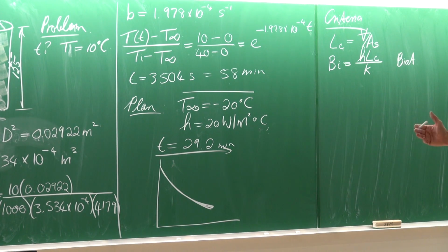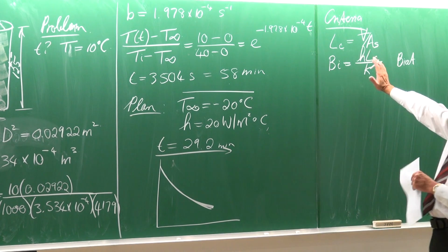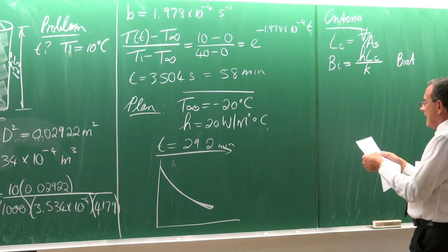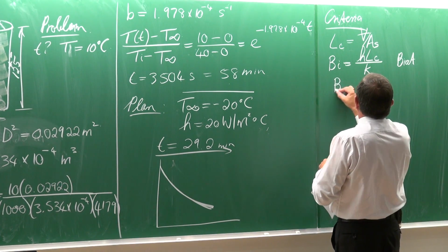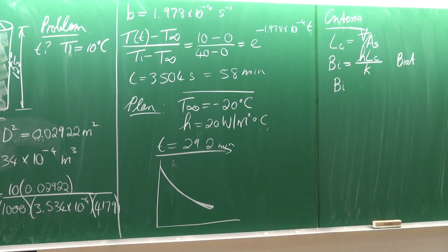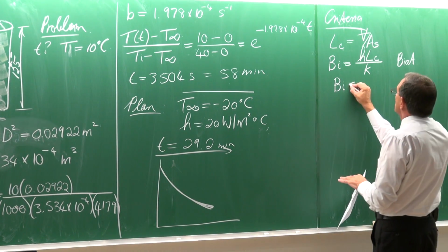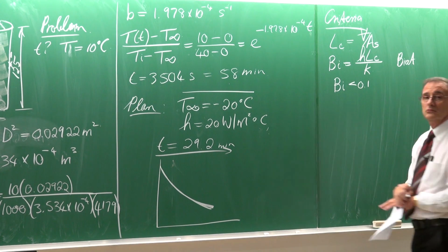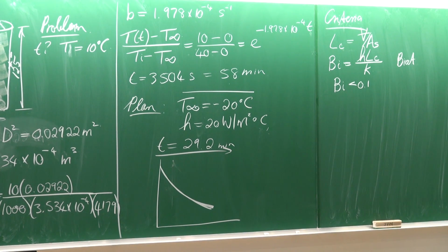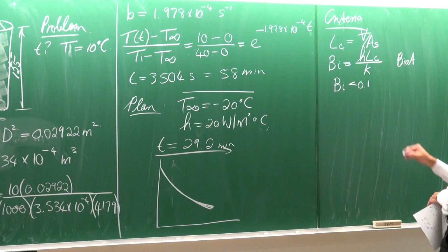Now, heat transfer, we're going to have many of these numbers. Now, this number, there's a definition of it, and what it says in the textbook is the lump system approach is valid, or it will give you good answers if the Biot number is smaller than 0.1.